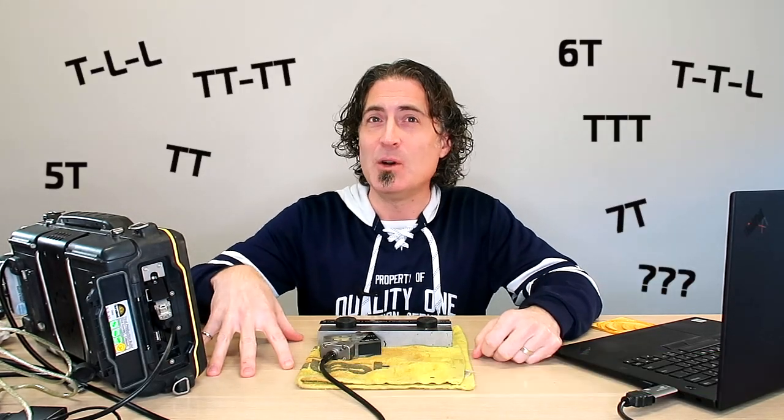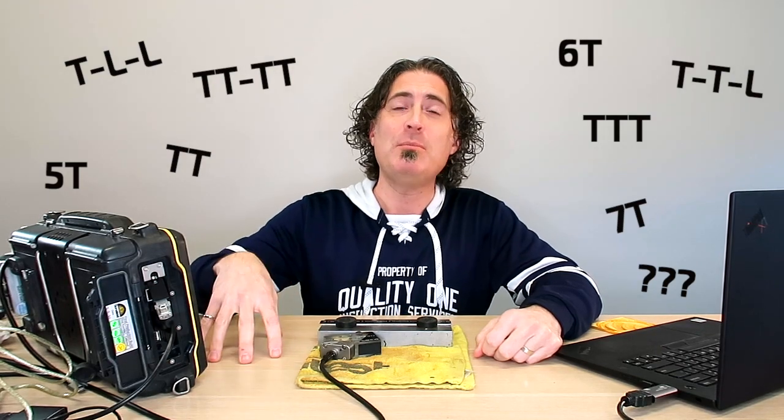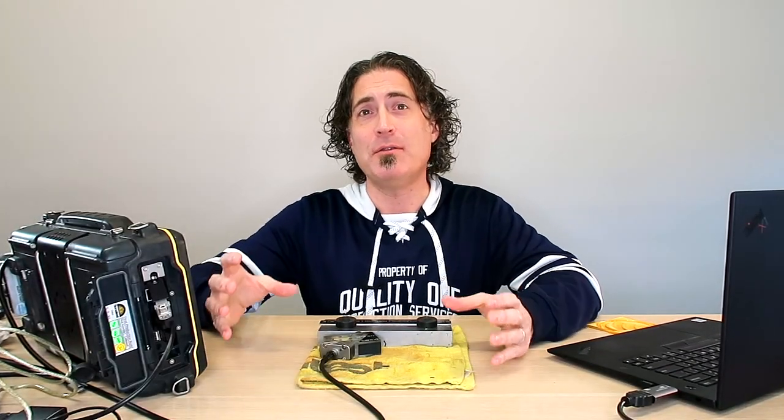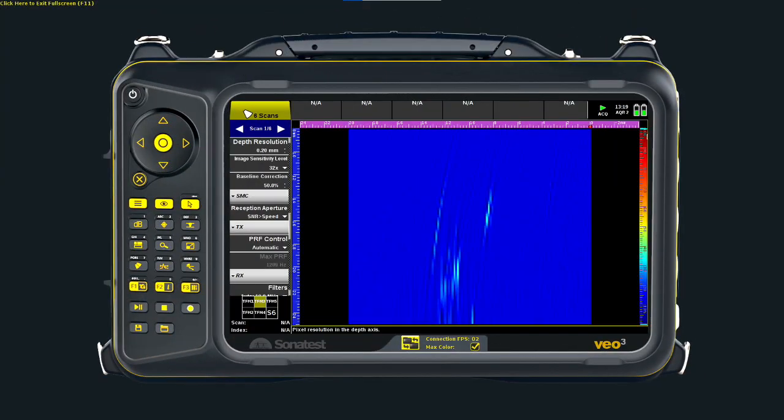With regular TFM, you've got a lot of modes to pick from, right? So you usually need to know a little bit about the type of flaw and the orientation of it before you pick the optimum mode to try to image that flaw. Just a few degrees of tilt or a few facets may cause a planar defect to disappear on some modes. This makes TFM challenging to use for detection. It's really easy to miss something if you pick the wrong mode.